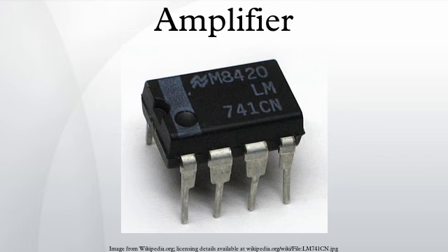The second harmonic can be used to reduce the overlap with edges with finite sharpness. For this to work, energy on the second harmonic has to flow from the load into the transistor, and no source for this is visible in the circuit diagram. In reality, the impedance is mostly reactive and the only reason for it is that Class E is a Class F amplifier with a much simplified load network and thus has to deal with imperfections.